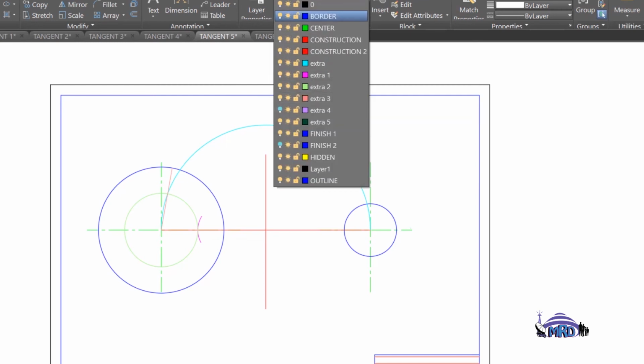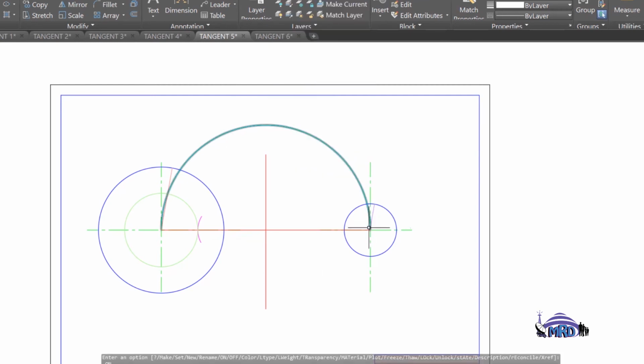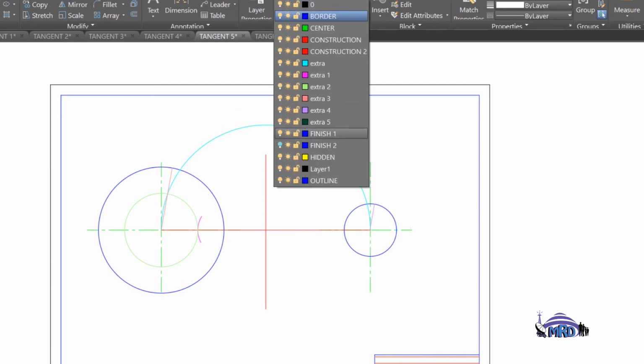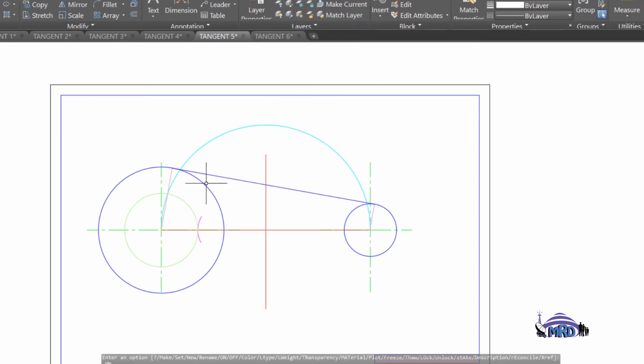So if we drop in that parallel line, then you would have that second normal in position, and then the tangent would be connecting these points of intersection as I have done now, and this would be an external tangent to two circles of unequal diameter.